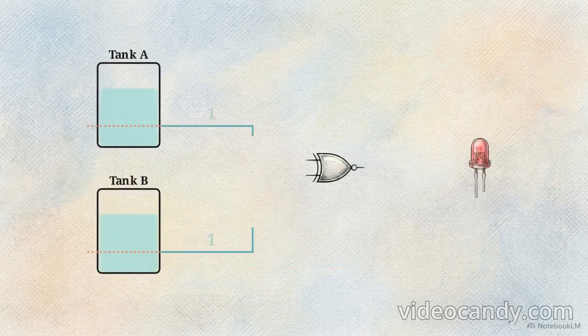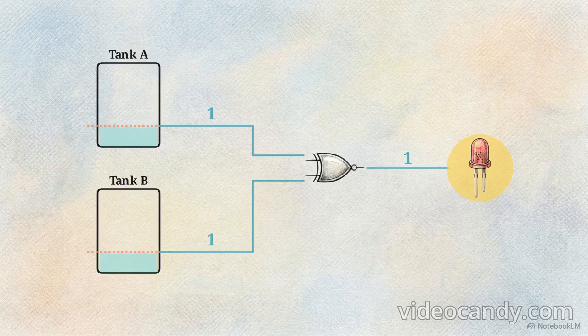low. To see why an equality detector is necessary, consider an industrial chemical facility. A safety system is tracking two massive liquid tanks, ensuring that both maintain a volume exactly at or above a 25% threshold. We wire the tank sensors into a single EX-NOR gate. If both tanks are safely above the threshold, the gate receives two high inputs and outputs a high, keeping the